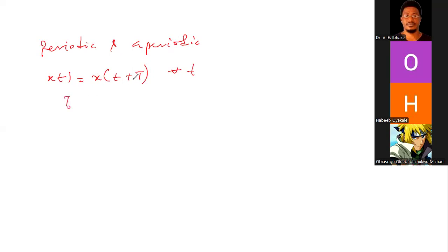Now, I already made mention of amplitude reversal, so we don't have to. So we have periodic and aperiodic signals. So when the signal is not periodic, okay? So when we consider a continuous time signal, say S of t, we'll say that it is periodic if it is defined over the fundamental time period, capital T, for all values of t, okay? Such that the fundamental time period T naught, which is not the same as T, is the smallest value of T, okay? For which the signal is periodic.